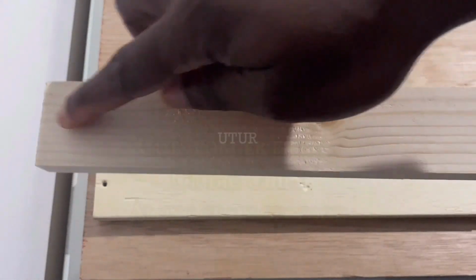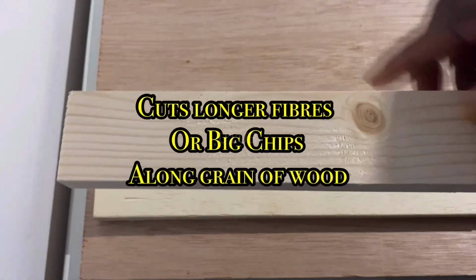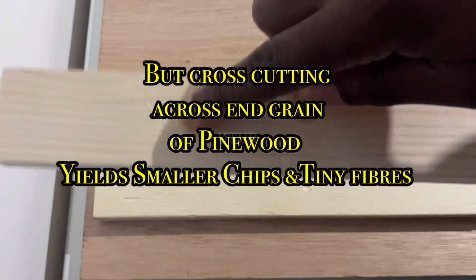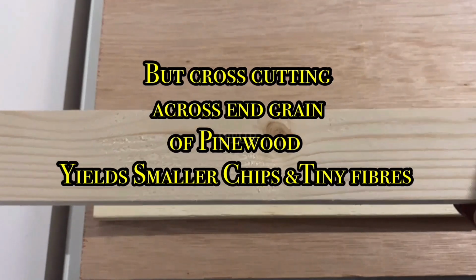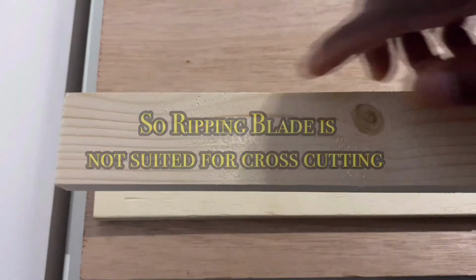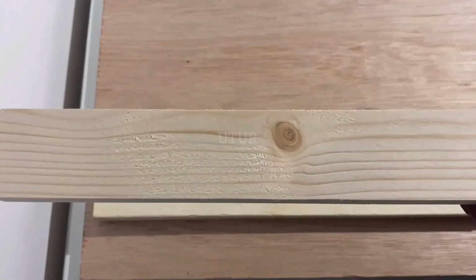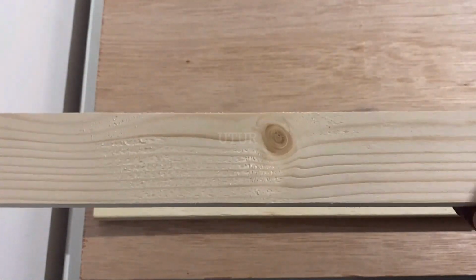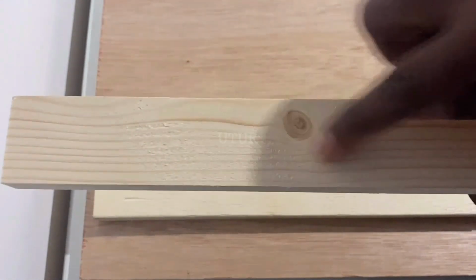The ripping blades typically have about 24 teeth. They have large gullets between each tooth to move out big chunks of wood. So it essentially cuts long fibres of wood or moves out big volumes of wood when cutting. So essentially you need big gullets for ripping, to rip in the same direction as the grain to enable big chips to come off the wood.